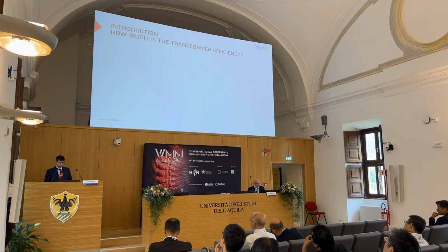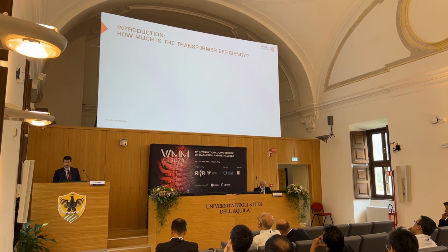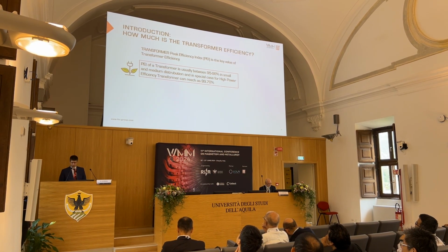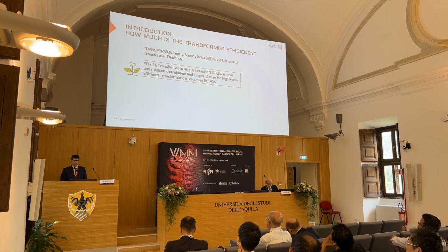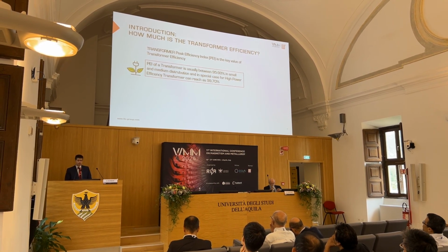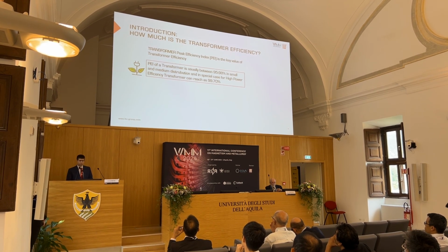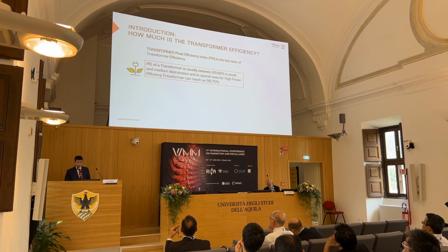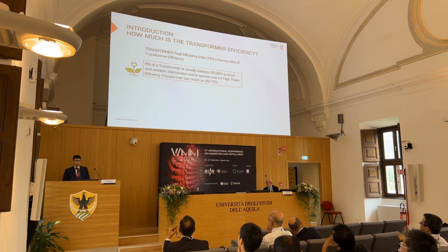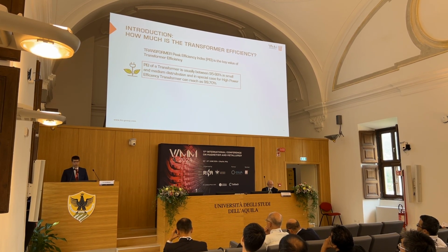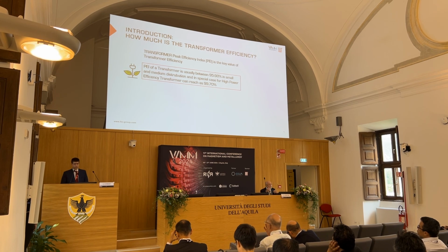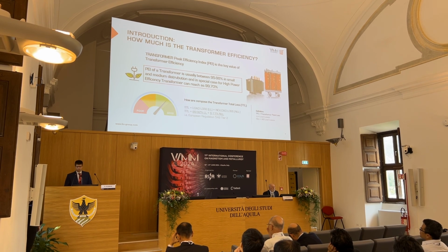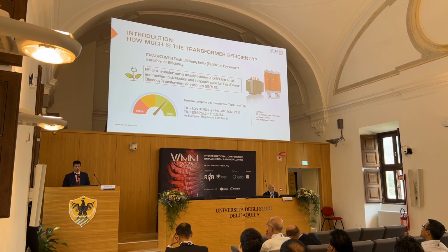So why is efficiency important in the transformer, and how is efficiency defined in the transformer? The main information that we consider nowadays is the peak efficiency index, and this defines how well the transformer performs during work. Several years of implementation have made these formulas more and more complicated, so nowadays the efficiency takes into account several data from the no-load loss and the core loss, as well as from the electrical copper and winding.